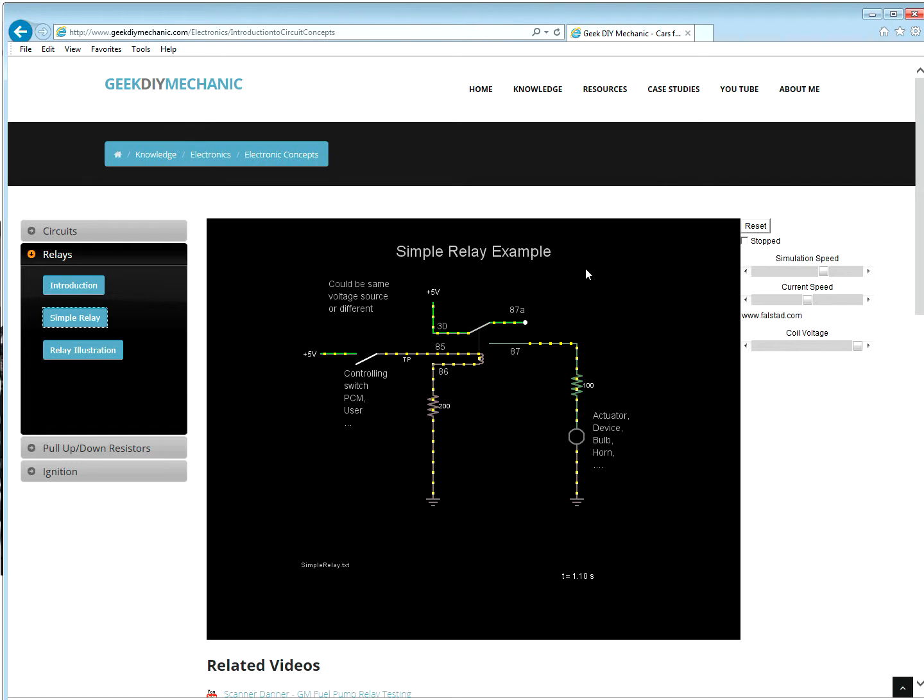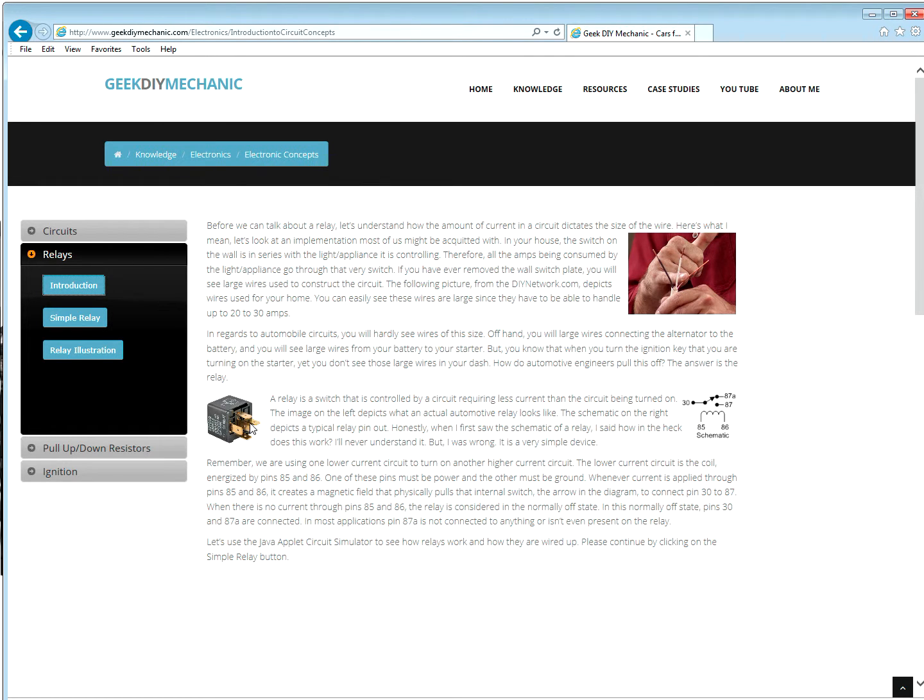So that would allow you, I'm just making up an example here, if you want all your red lights in your car to be on when your ignition is off. Of course, you would never want that, but just bear with me in an example. But when you want it on, all your green lights would be on. From my experience, most of the time, cars don't use 87A. Many times, the relay will be missing the center post, which I believe is 87A.